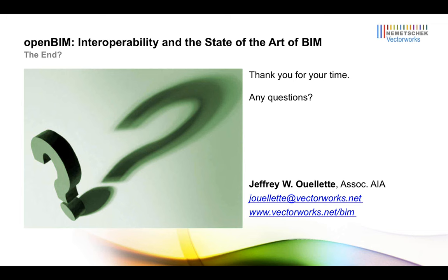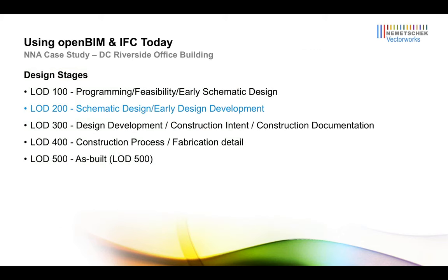In going through the E202, the AIA LOD, the level of development, it's very subjective. What can be considered 100, 200, 300, up to 500. There's nothing that really defines what makes up a 100 versus a 400. And I'm curious as to what you used as a benchmark, because I've developed my own benchmark for it, but this is one of those aspects that really should be more clearly detailed and more clearly laid out.